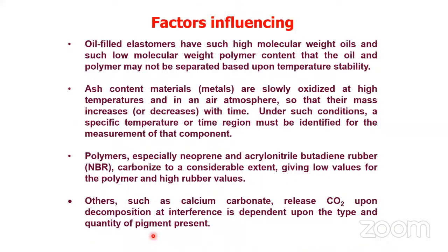Okay, so what kind of factors affect thermogravimetric analysis or TGA? Oil-filled elastomers have such a high molecular weight of oils and such a low molecular weight polymer content that the oil and polymer may not be separated based upon the temperature stability. This is nothing but a material-related factor which affects the TGA.